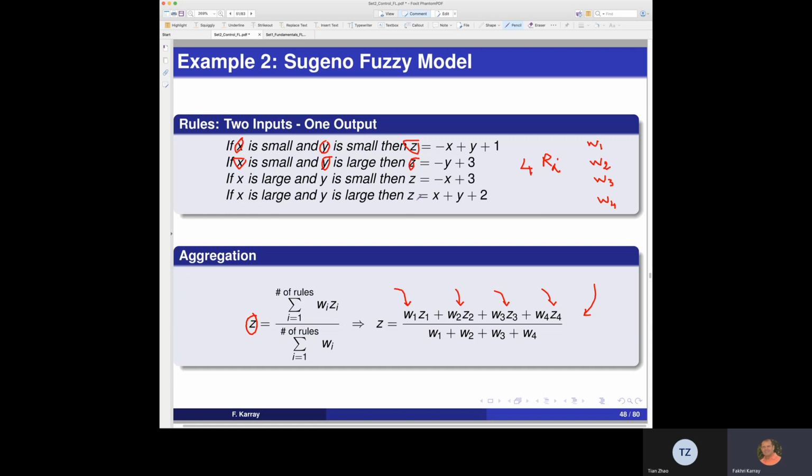So because of that, we are utilizing a system that has a better defuzzifier, such as the mean of max or the centroid, the bisector of area, or the largest of maxima or the smallest of maxima. Here, the difficulty is in obtaining the representative of the outputs of the consequence in terms of a function of the variable. You can see here, to obtain this particular first order polynomial, it's difficult. It's not easy to do that.